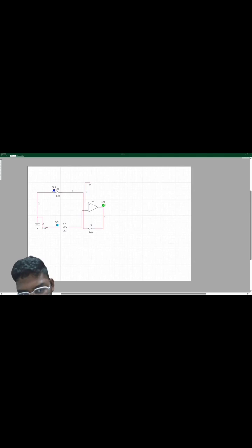For the first step, assemble a circuit that consists of a 12-volt DC supply, a 1 kilo-ohm base resistance R1, a push button switch S1, an NPN BJT, and an LED in series with the collector. The push button and the resistance connect to the transistor base. When pressed, S1 allows a small base current which controls a large collector-emitter current.